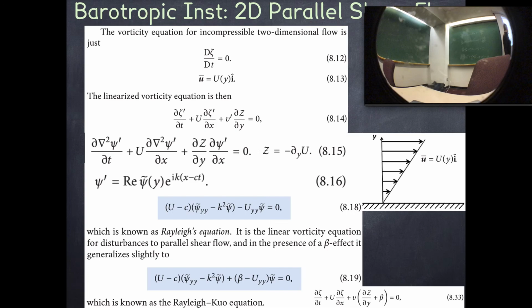But this equation applies to all profiles like that. And I could put another boundary condition on the other side, or I could do all kinds of things, but as long as there's no V, there's no pressure anomalies in the initial condition, there's just a shear flow of U as a function of y, a parallel shear flow, then this equation is a constraint.